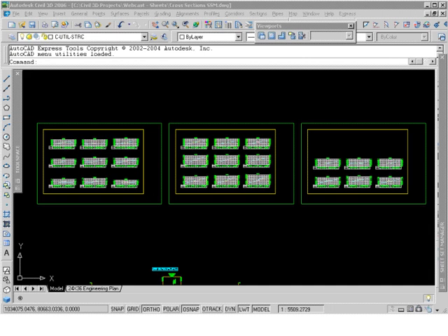And then I'd like to take a look at something else that's also built in Civil 3D, which is Map. And Map has a new feature this year with Map 3D 2006 called Map Books. And it's a feature that they've revamped for this release. And it actually takes advantage of Sheet Set Manager, but automates the layout of our plans a little bit more. So again, we're going to take a look at using Sheet Set Manager, and then taking a look at Map Books itself. Well, let's just start out.